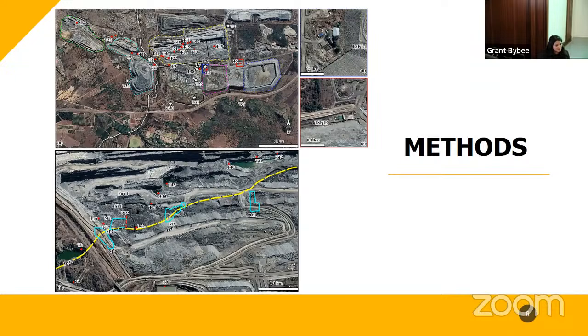Accelerated weight drop. Yeah. It associates more with the penetration depth to which your seismic waves can propagate. So with the hammer, you're only going to get more of your near surface, whereas the weight drop can go to depths of, I don't know, about 3 kilometers.